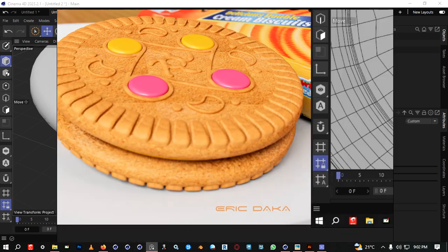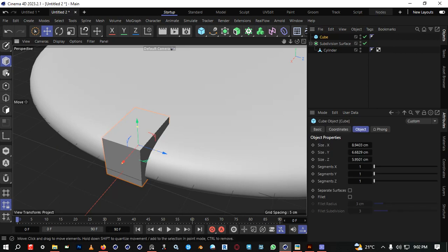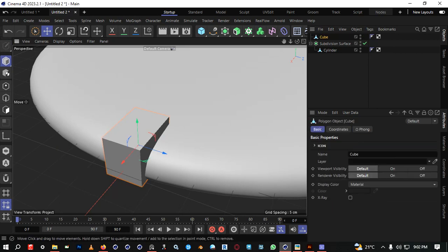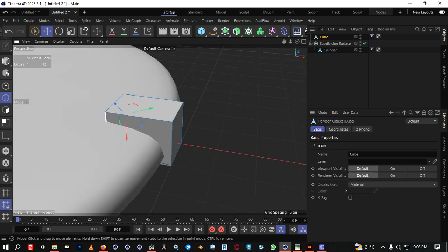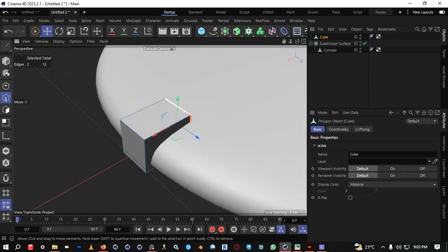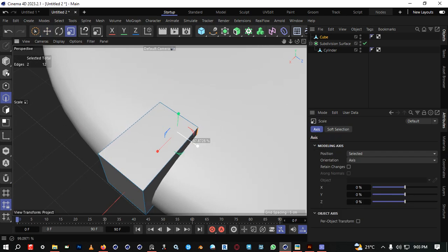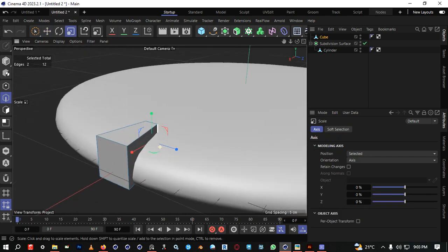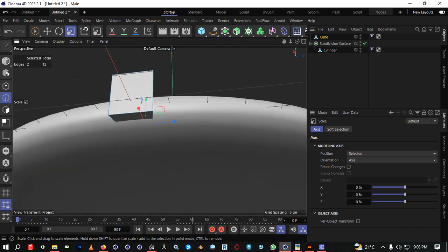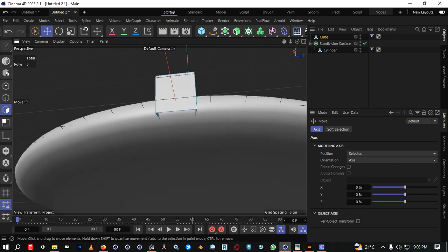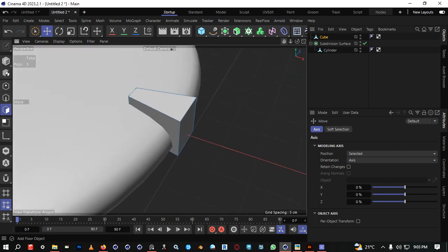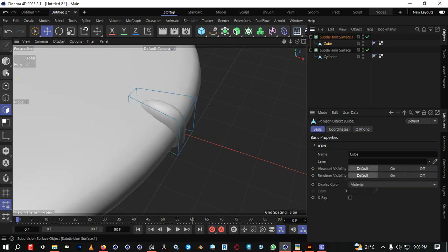If you see, oh, the front part was big, then the inner part was small, so I had to make this editable, just the way it is. Then I had to grab these inner edges, then I had to scale them to give them that kind of shape. And since we're not going to be able to see the bottom part, I didn't see the necessity of adding it, so I just deleted the bottom part. Okay, then I added in a subdivision modifier for this, so that we can work from there.